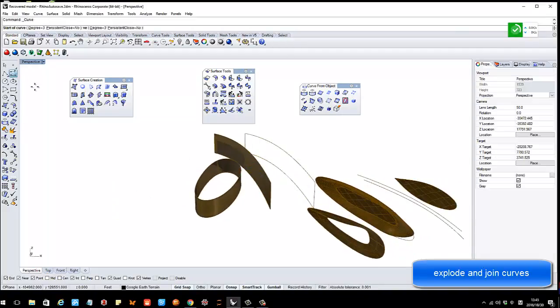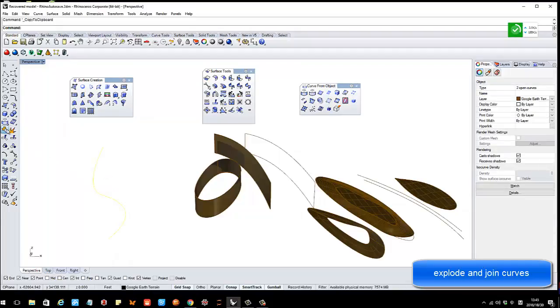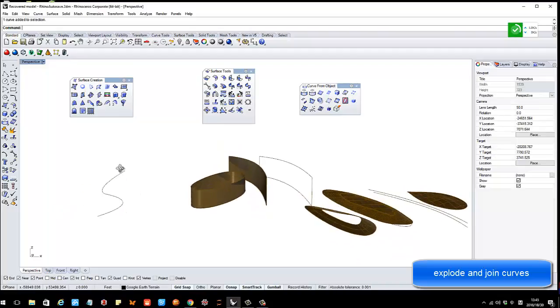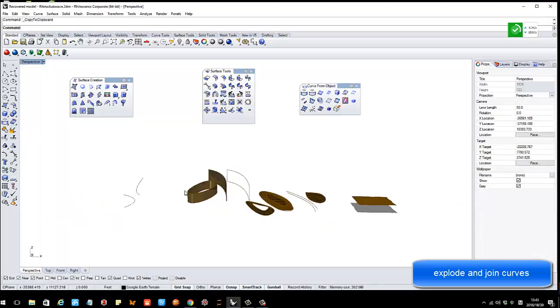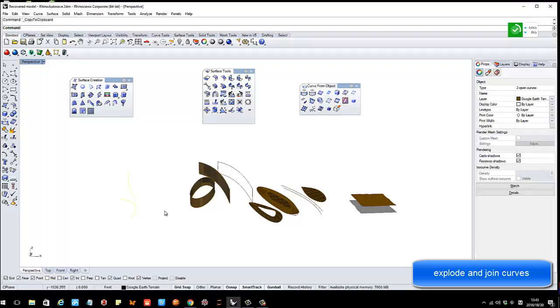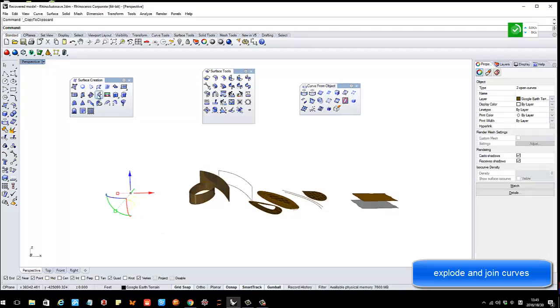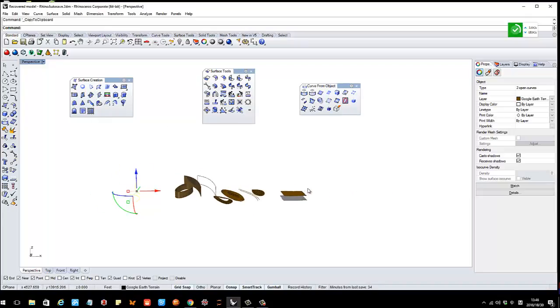All right. Let me try and see here. This is one line, and this is the other line, right? I select all of them, I join them, then they turn into a single one, okay? Just one, right? But if I click it again and click explode, then it explodes, right? So these are all the things to remember, okay? But really, there are a lot of tools here. You don't have to know every tool, okay? Just the tools I mentioned. I think there are several, right?